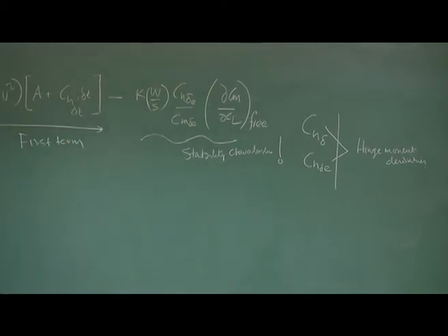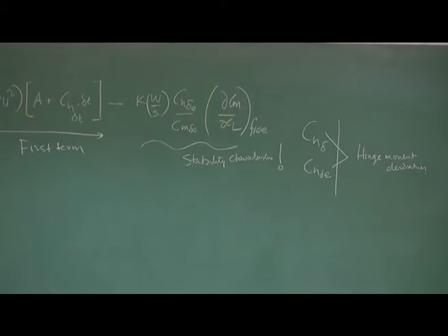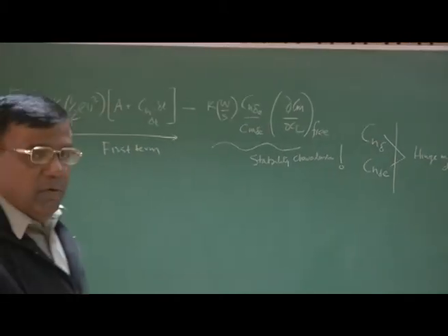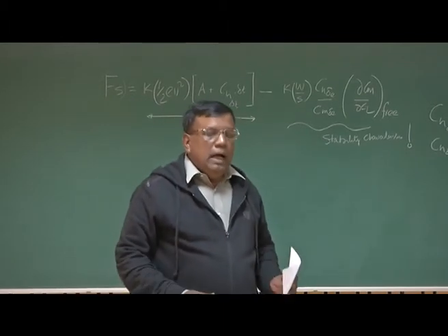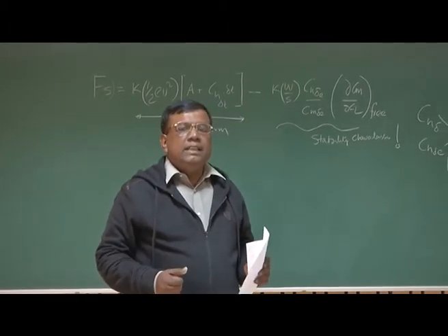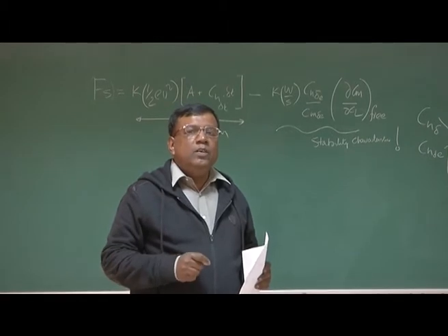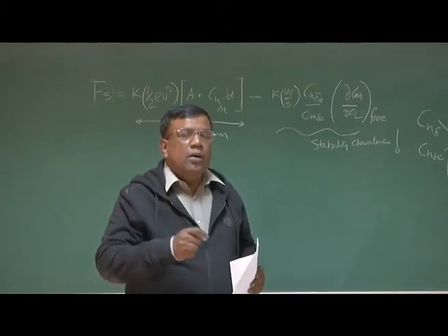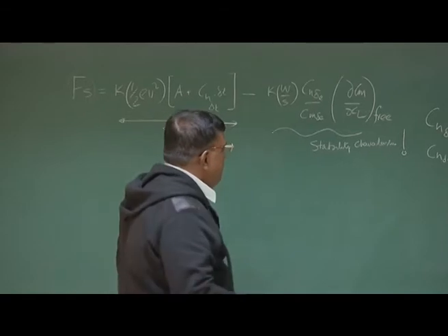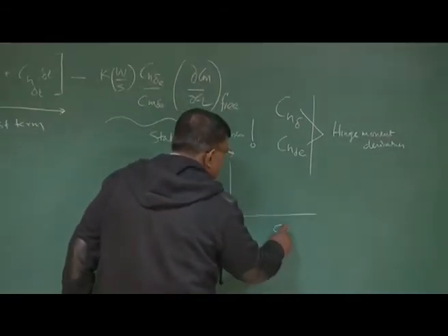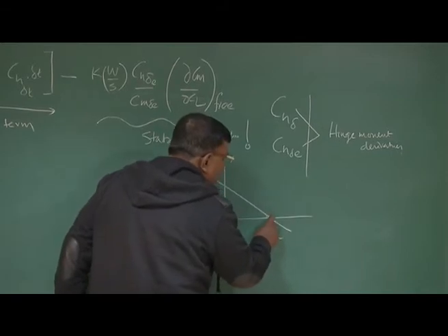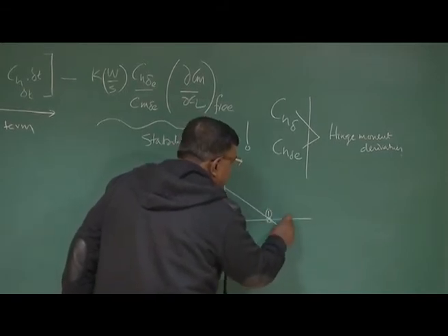This is something surprising, right? So we need to ask ourselves a question: whenever we are talking about stick force, what are we actually doing? We should know this very clearly. I am applying stick force to change the trim of the airplane from one equilibrium to another, one trim to another trim. If I have Cm and Cl here, I was flying here, and I want to go from one trim to another.